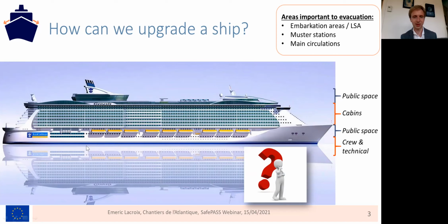A big portion of a ship's length is used, and you can't really use the fore and aft anymore, because those are areas where the ship generates undesired waves. So you want to try to avoid these areas. Plus, you have a propeller in the back of the ship, which is generally not a good idea for LSAs. So, okay, longitudinally, we can't change the LSA positioning. Let's try to move them up or down. Well, it's complicated also because,